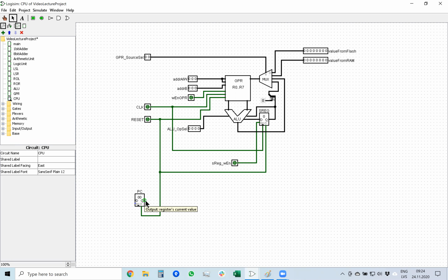And only on very rare occasions, I think in MSP430 microcontrollers from Texas Instruments, the program counter resets to all ones, and the beginning of the code is actually located at the end of the flash memory for this one particular type of microcontroller. But as far as I know, all other microcontrollers start the program from 0. Okay, so